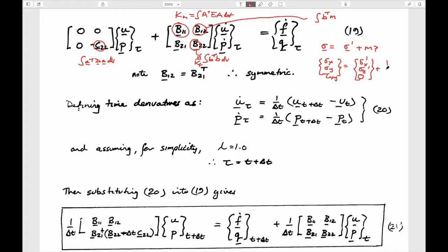And this M matrix, which was 1, 1, 0, it could be alphas, the Biot coefficient could be in there as well, operating on fluid pressure, which is a scalar. And you remember that this, and we didn't note it at the time, is due to the fact that fluid pressures act only on the normal stresses, and so there is no such thing as an effective shear stress. And I suppose the corollary of that is that we talked about the volume changes.